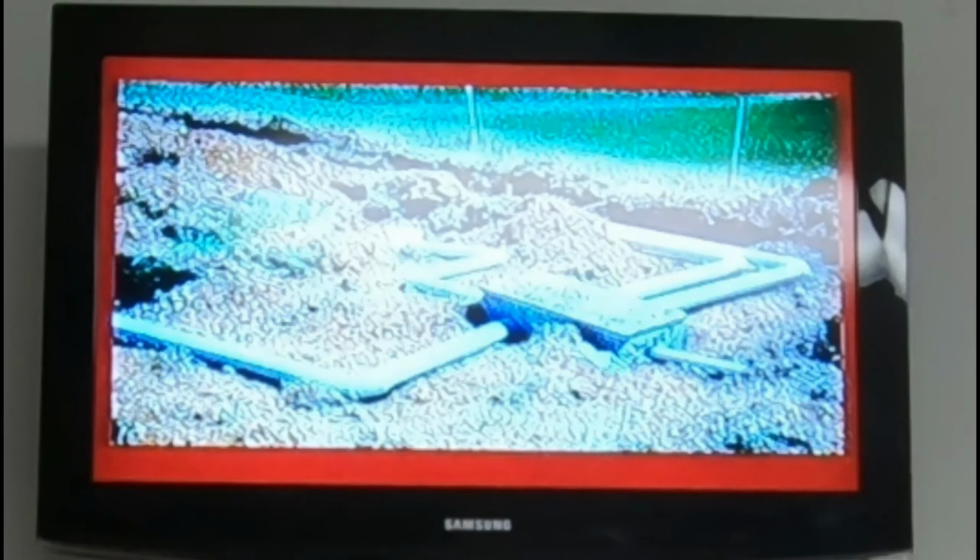All independent sewer pipes coming out of the distribution box shall be installed level at the same elevation for 2 feet. Beginning 2 feet from the distribution box to the beginning of the perforated pipe at the start of each absorption trench, a minimum of 2 inches downward grade is required.